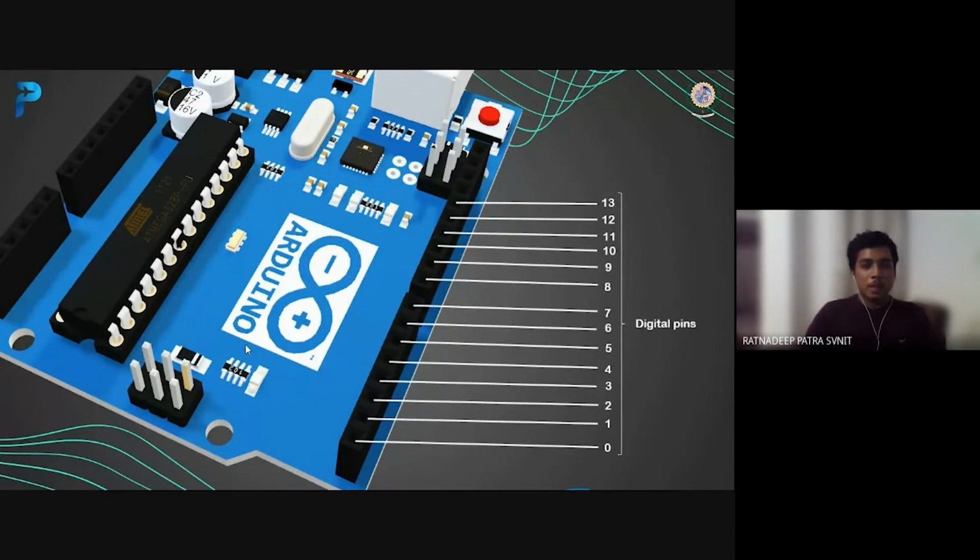As these pins can be used for both input and output, while programming the Arduino we have to mention whether we are using these pins for input or for output. The analog pins that we saw earlier, A0 to A5, can also be used as digital pins. While programming, we just have to specify that we are using these pins as digital pins.